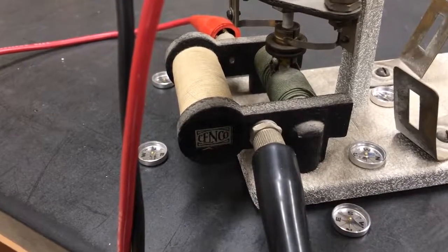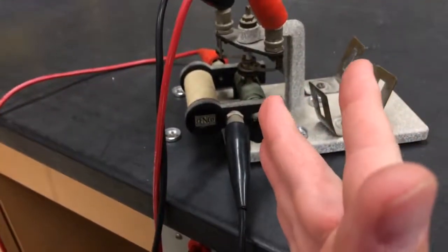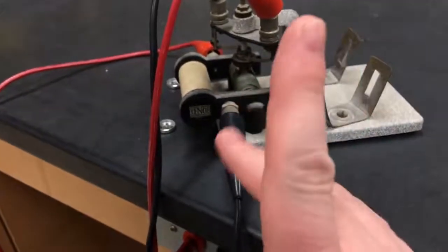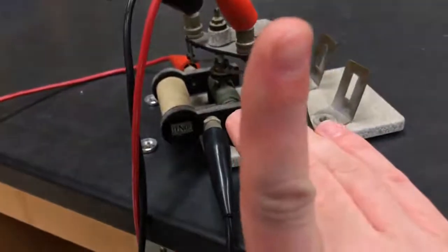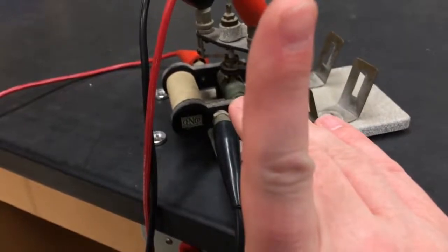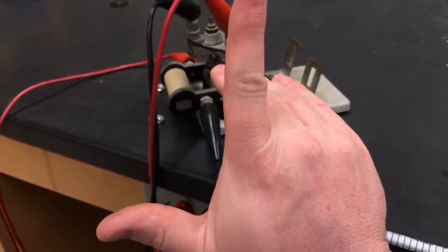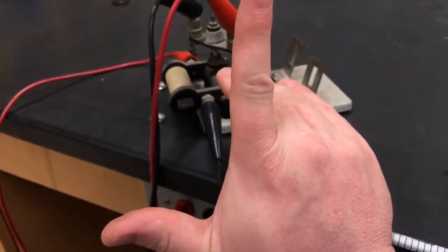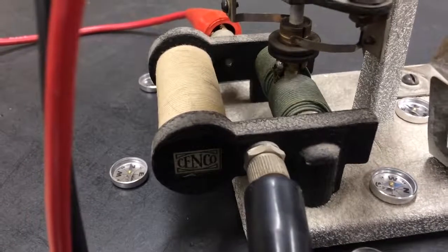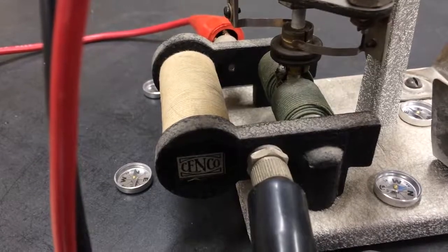Let's do the right-hand rule and see what happens. So we know the magnetic field is pointing in the direction of my bottom fingers from the compasses. So we'll point it that way, and we'll know from the argument that the current is heading clockwise, that the positive charges are heading towards the ceiling, like my index finger says. What that means is we should get a force on the coil of wire in the direction of my thumb, towards the left. So that's going to pull the coil towards the left. And because of the way it's wired, the other side is actually going to be pushed away.